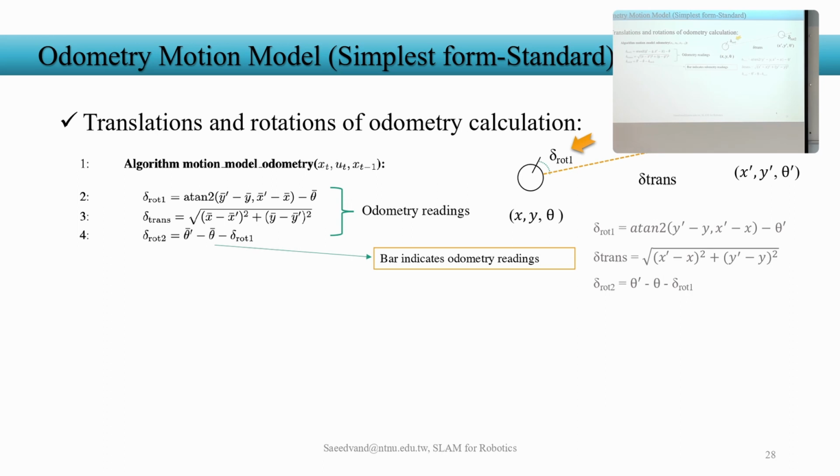Now we want to pull it all together and bring the odometry reading and control command reading and show it in probabilistic form of the error: what is the probability of the error that we have based on the control commands and odometry reading. Consider this again, keep it loaded in your mind. The names of the variables are a little bit different, but it is the same concept and the same calculations.